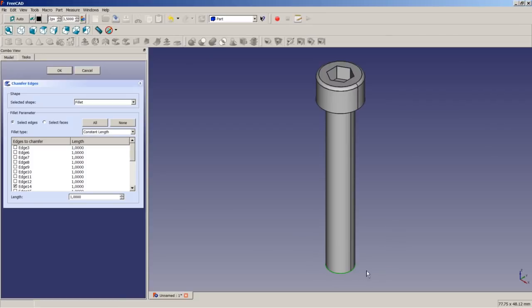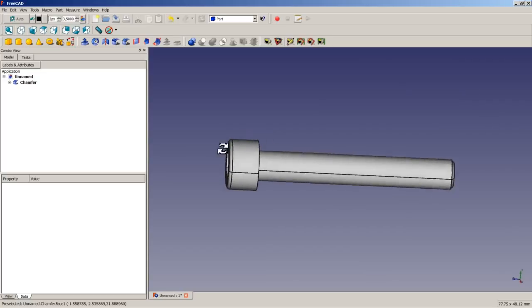So if you need another angle, and when we try to model realistically, we are facing the restriction that a metric thread uses an angle of 60 degrees. It is not possible to apply a chamfer of 30 degrees with this operation here. So in this case, I apply a chamfer of, let's say, 0,5. It's just an optical representation. And I'm done here.